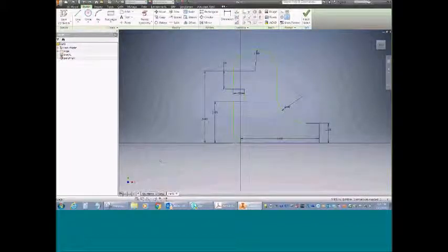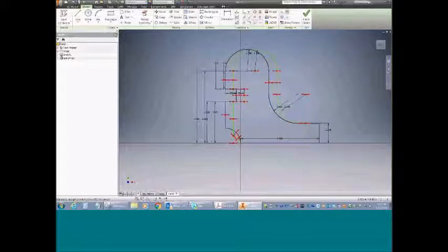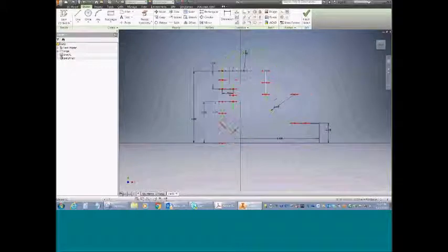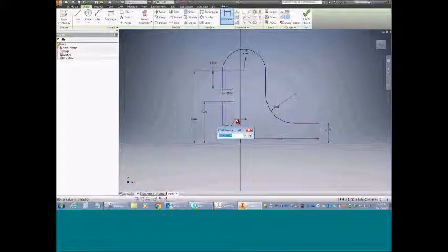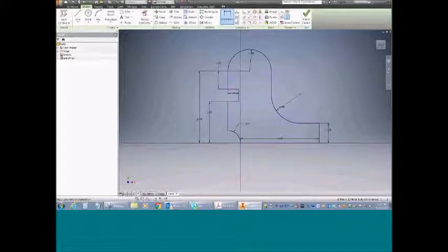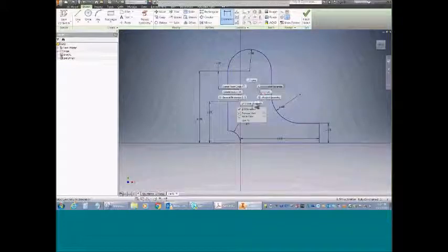There we go. So if I turn on show my degrees of freedom, it shows me what's allowed to move. So without that radius dimension in there, all of this geometry is allowed to move in the direction shown. So sometimes that helps me identify what's missing and what flexibility I have. So put that dimension back in there. There we go. So you would just finish this,